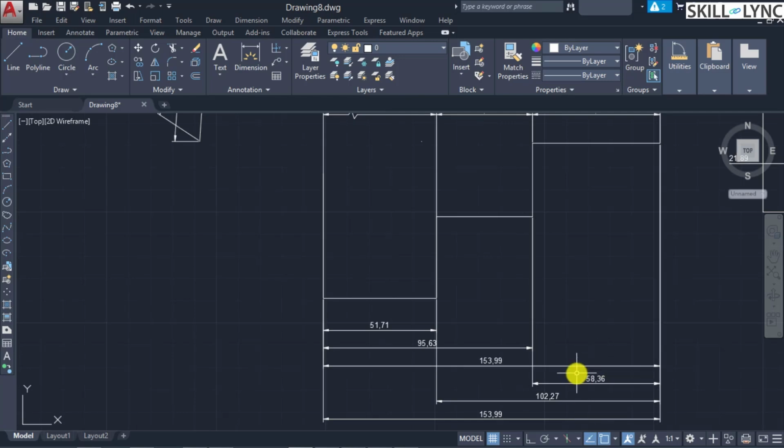So this dimension space command can be used extensively to make sure the dimensions are very readable, because at the end of the day, the production specialist and the inspection specialist should be able to easily understand the dimensions and drawing intention. So this is the spacing of the dimension elements. So next what we have is the breaking of the dimensions.